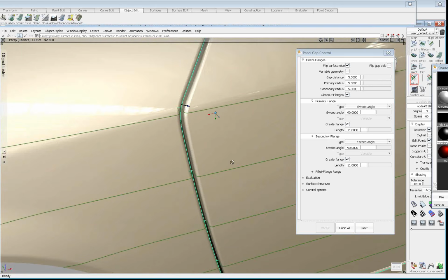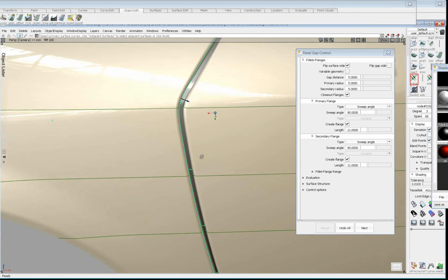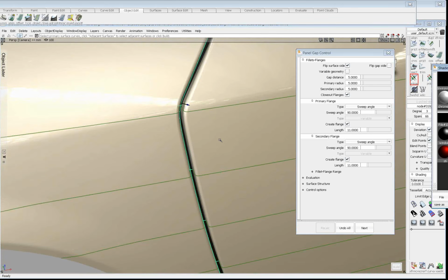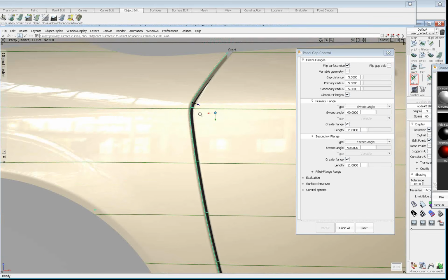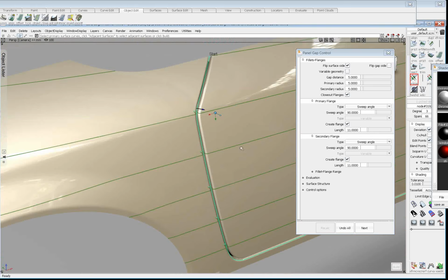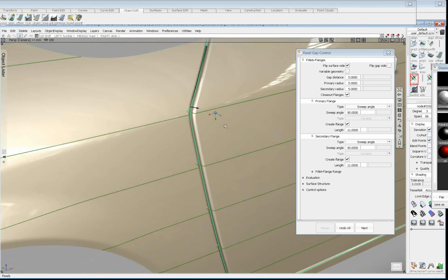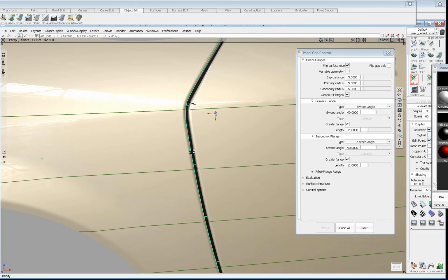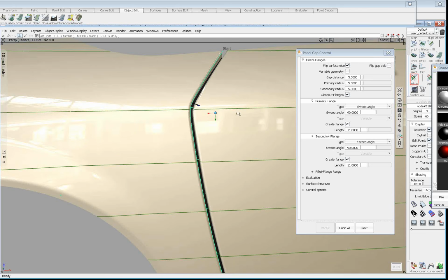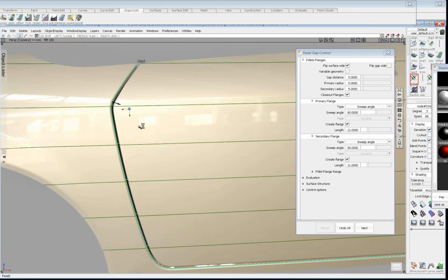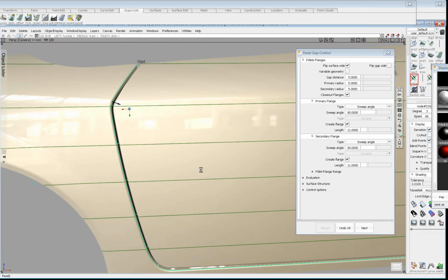So in terms of visualization, maybe not glossy, that's not that pretty really. There we go. So in terms of doing a visualization, how quick is it to just use the panel gap, add the closeout, and be able to select it and put a blackout on it. This is a pretty significant sized gap for a door, but I think it illustrates the point easily enough. You also may want to use those closeouts when you're doing milling, just to keep the cutter on the clay mill from descending past your model. So it's a nice little way to address that.